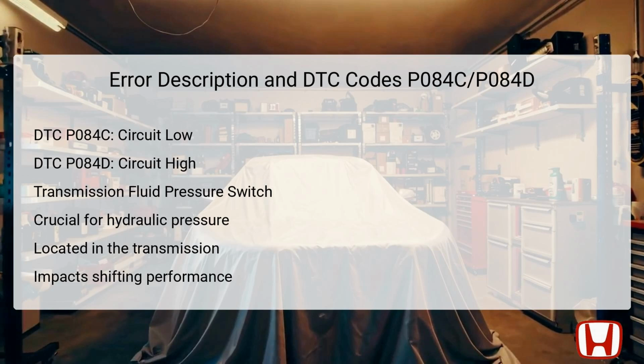It is essential to assess the entire circuit, including connections and the TCM, when these codes are triggered, as each component relies on the others for proper functioning. This detailed diagnosis is necessary to eliminate potential issues effectively.